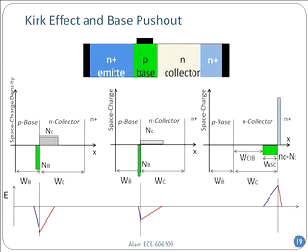It will completely disappear because there is no charge. And that's what is called base push out, because base has been pushed out all the way to the collector. Now you have a humongous base, lots of recombination, your transistor is all gone. This is all a consequence of low collector doping. That's why you get into this trouble.